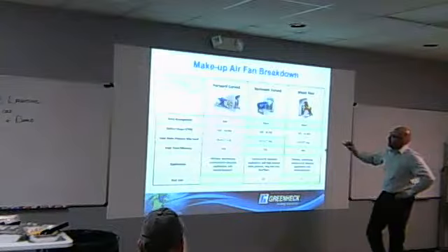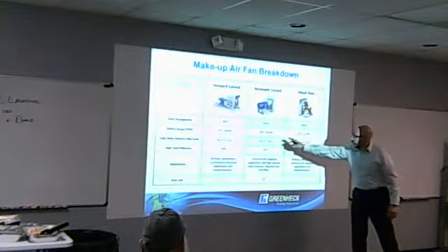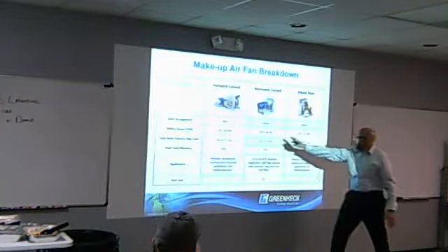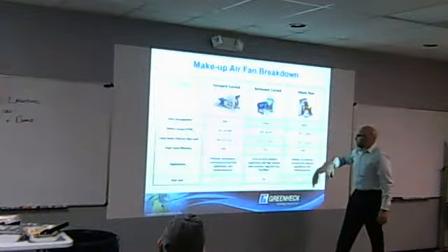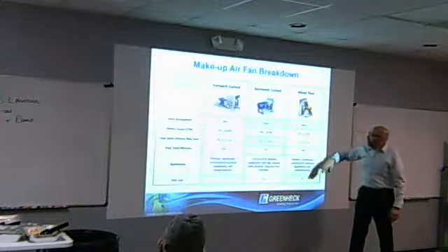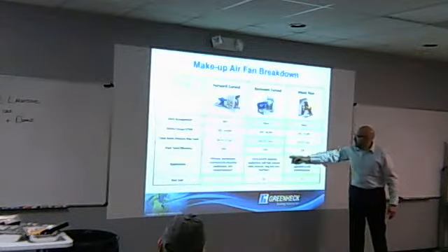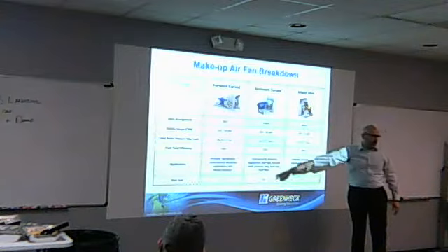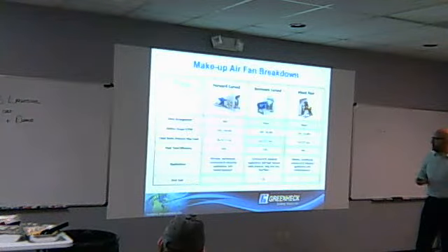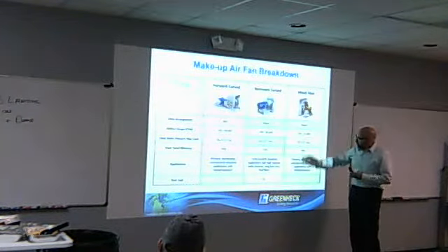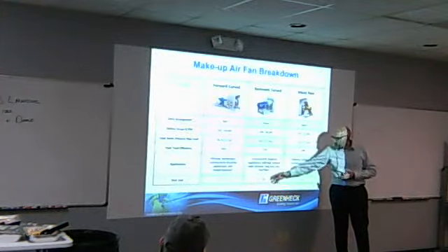So in terms of pros, direct drive eliminates the maintenance of the belts. Volume wise, it might have a little greater volume than the other two, but we lose a little bit of static pressure capability. So highest static is in the backward curve. Mixed flow is still up to 3 inches, but now you get into energy and peak total efficiency. You see where these greatly outweigh the forward curve. So more and more movement towards these backward curve or mixed flow wheels. And then in terms of dollars, you're not paying that much more, almost similar cost to this arrangement. This wheel is a little harder to make, so it does cost a little bit more.